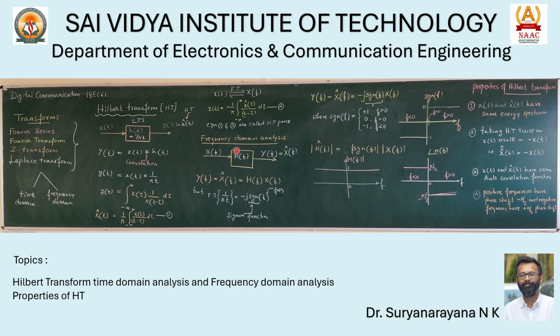But in the frequency domain, the Fourier transform of h of t is given by minus j signum function. That means this is the Fourier transform of h of t in frequency domain. So on substituting this in the equation, we get the Hilbert transform in frequency domain as minus j signum function into x of f.